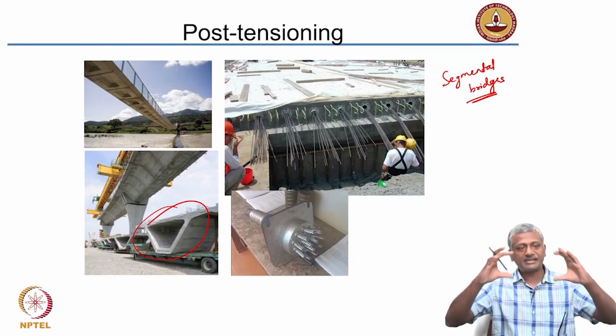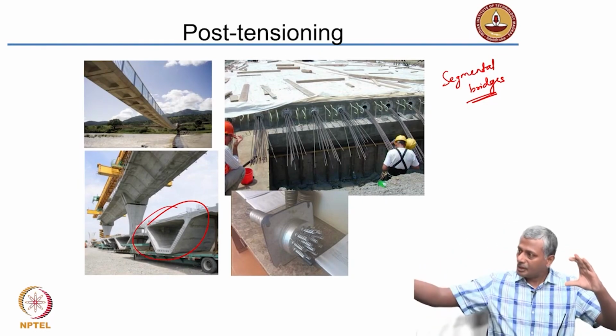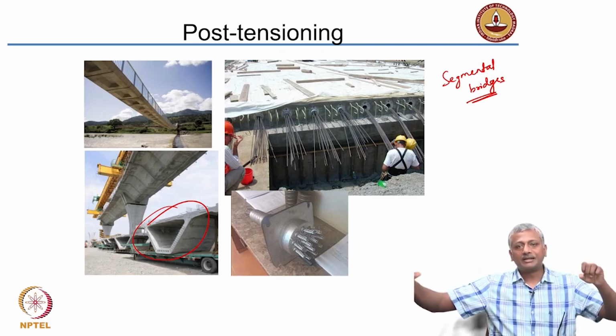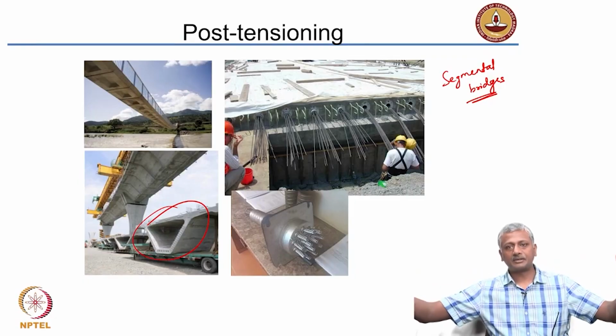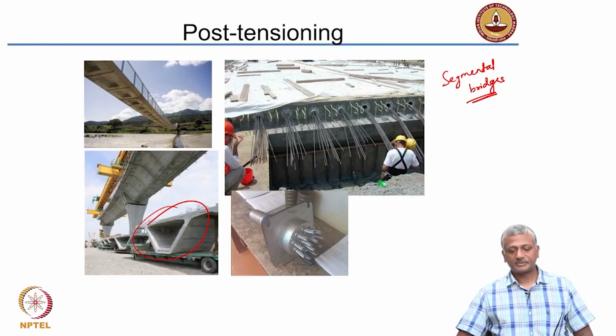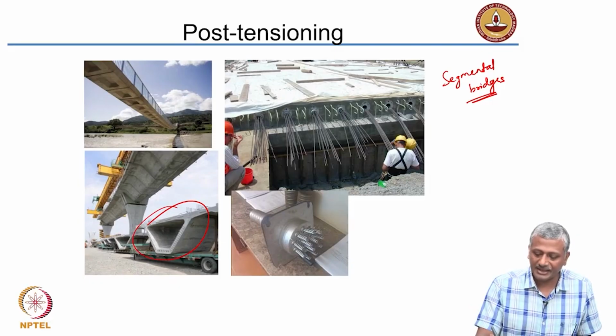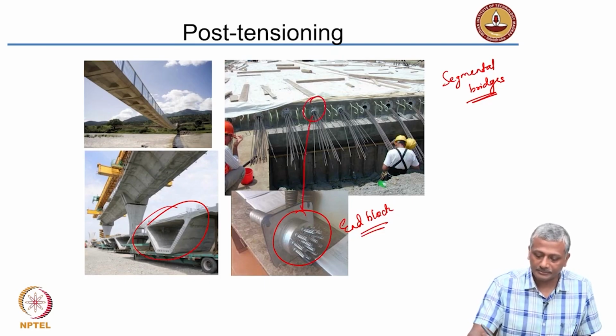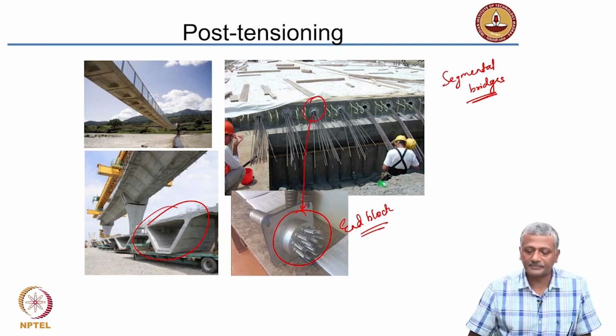So, you have several of these segments put against each other. You push the pre-stressing strand through it and then stretch the strand, passing the compression onto the pre-stressed members, and that is basically what is shown here. This is again an end block showing where the strands are actually coming out, just like what is here. It is a magnified view of what you see there, okay.